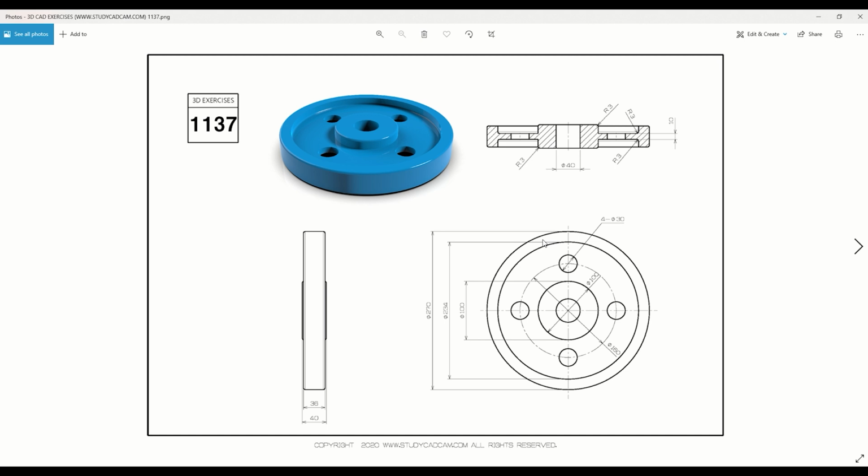Here are the given dimensions and views. This is a section view. In the section view we can see that in between, metal is there, and the other two sides have some metal removal. The material in between is 10 mm, the outer diameter they given is 250, and the inner diameter will be 234, right? Let's see what we need to do for a revolve.